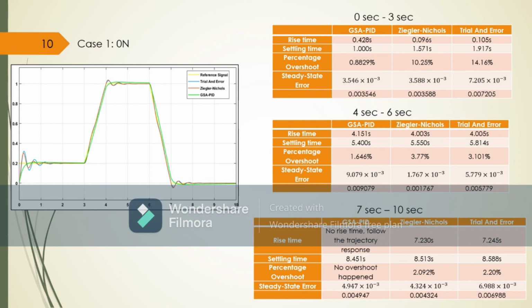According to the graphic analysis, the GSA PID achieves the satisfactory performance of the designed PID controller compared to other methods. The PID controller with the GSA for the EHC system tracks the reference segment smoothly and continuously compared to the trial and error and synchronous method. The drawback of synchronous and trial and error method is captured clearly when significant oscillations are produced during the simulation based on the figure. The oscillations are produced by both tuning methods.